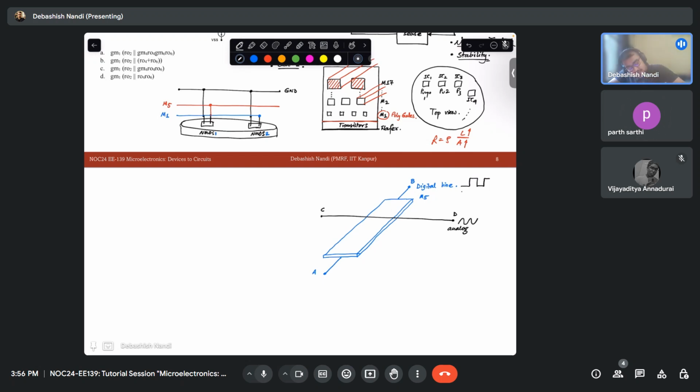So what is the frequency of this pulse? Let's say if I give you this kind of transition, is it an instant switch? What is the frequency, very high or very low? Very high. Switching frequency is almost infinity, right? So don't you think this will create coupling capacitances through the dielectric in between, because between these metal layers there will be SiO2? So at this high frequency, these two lines will be coupled to each other. You got this, right?